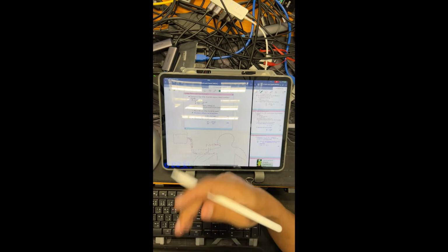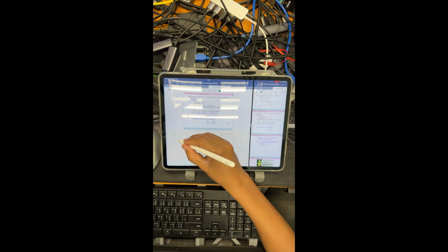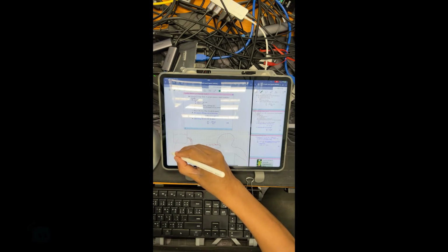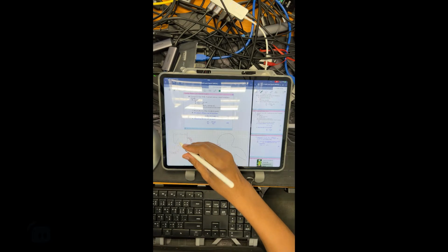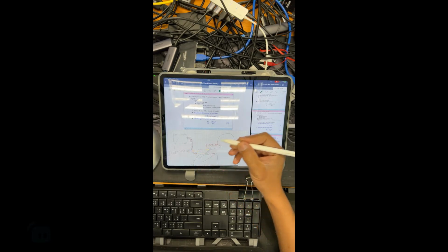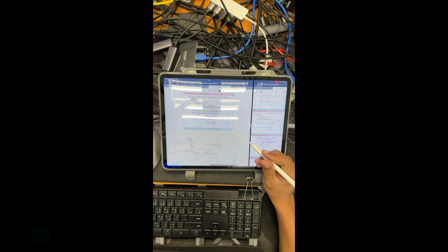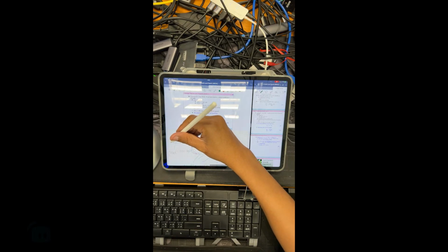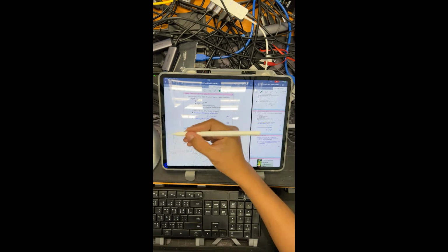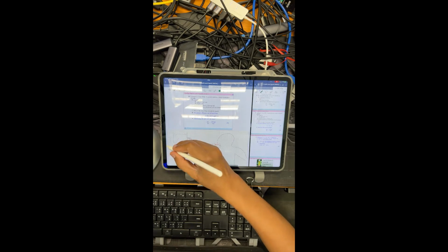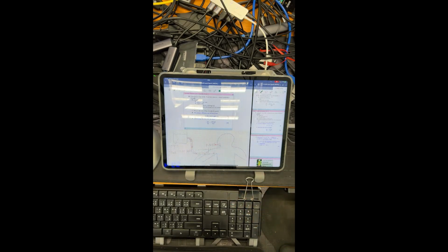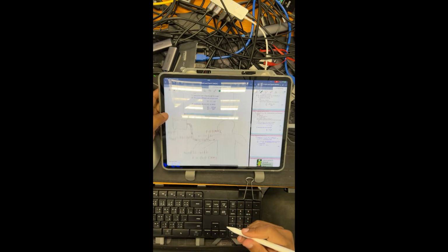And the density of the blood inside the container, rho of blood, is 1,050 kg per cubic meter, right? And the bottle supplied is higher. It's 5, oh no, not 5 meter, 5 meter is too high. It's 0.5 meter above the needle level, right? It's 0.5, so h is right there.